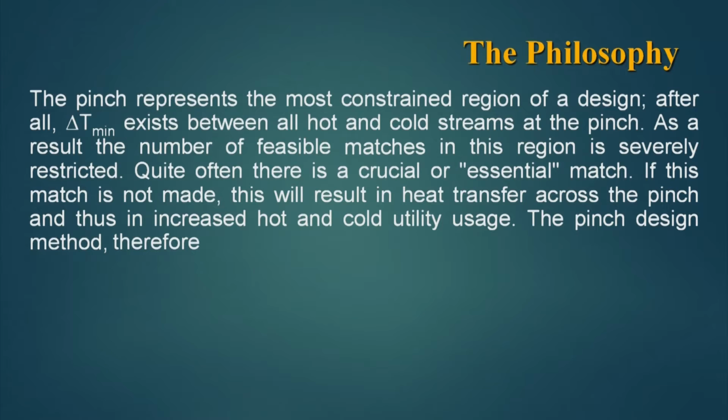Due to this, sometimes the concentration of area of the heat exchanger network at the pinch is high, and these heat exchangers also contribute towards the total cost of the heat exchanger network, and hence placing matches at and around the pinch is very important.